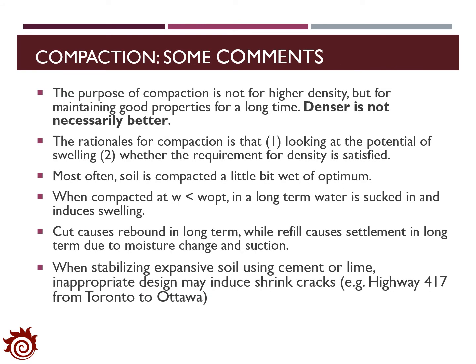Here I summarize some comments for soil compaction. First, the purpose of compaction is not for higher soil density. Instead, it is applied to enhance the properties of the soil for a long time. Usually, denser soil is not always better for the pavement design.